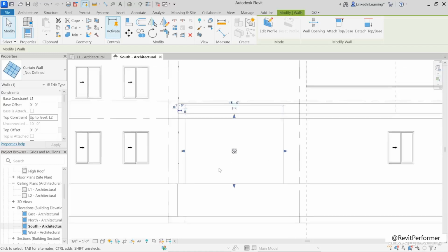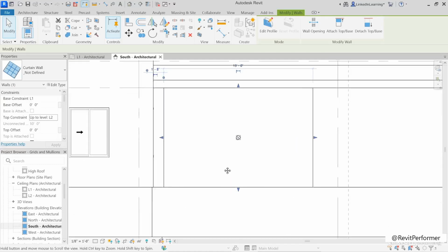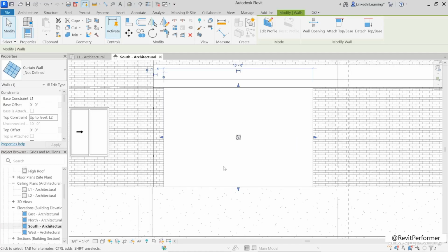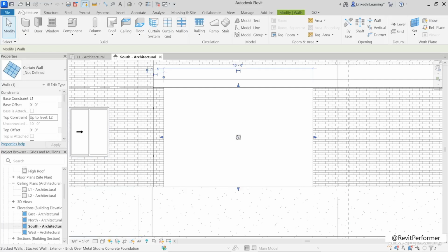And that will shorten it down to just underneath this canopy that we have in the front of the building here. And now I'm going to zoom in even closer so that we can begin customizing the layout of our design. So to do that, we go to Architecture and we're going to use the Curtain Grid tool.